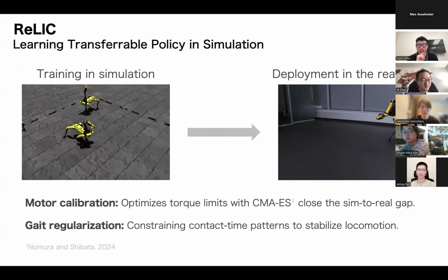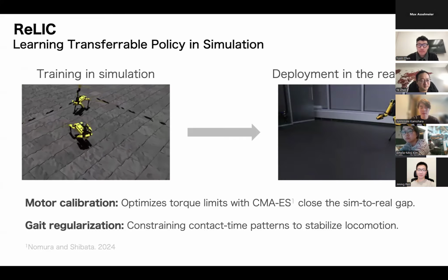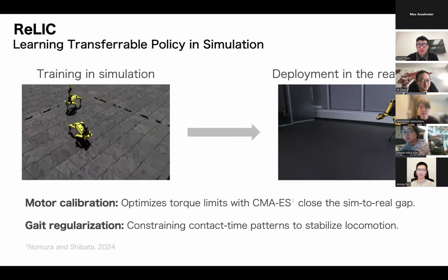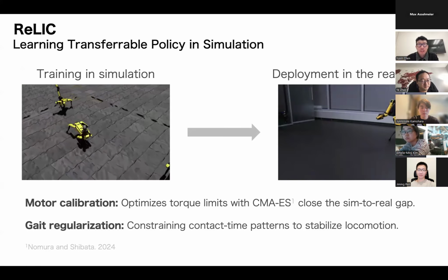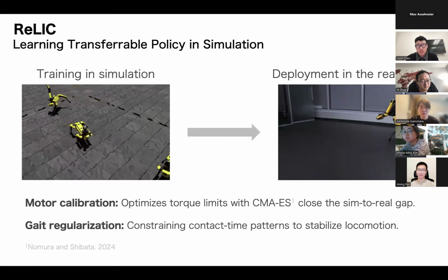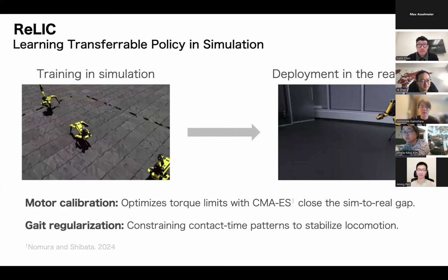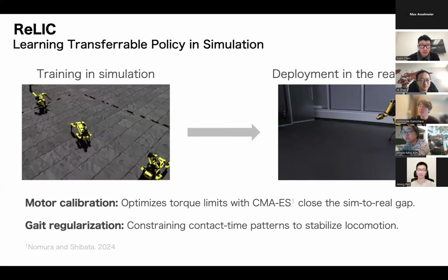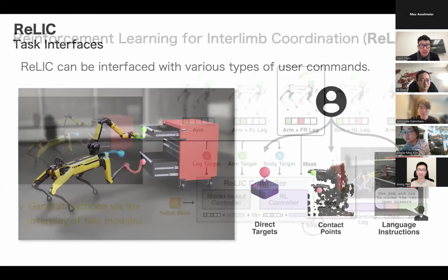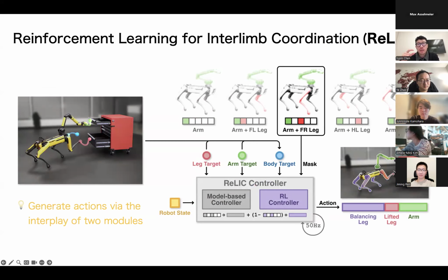I guess your RL controller takes the mask information so that you can switch between 4 leg locomotion and 3 leg locomotion plus 1 leg in the air, right? Yes. The mask is also an additional observation fed to our controllers, and it also feeds at 50 hertz. That's why we can dynamically switch during the execution, and it can suddenly just switch the gait.